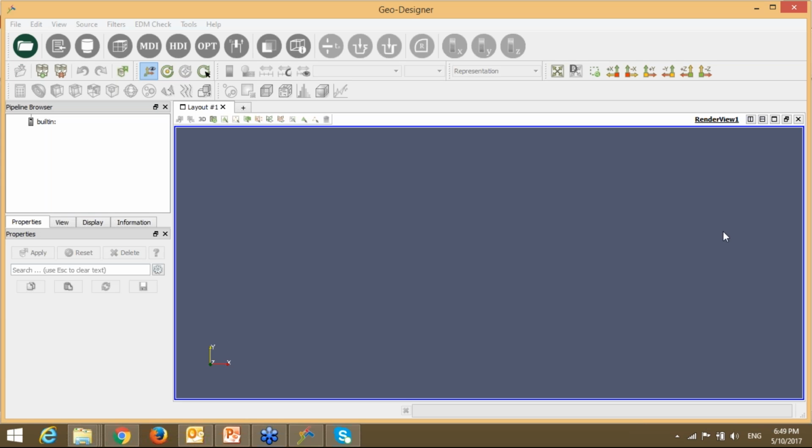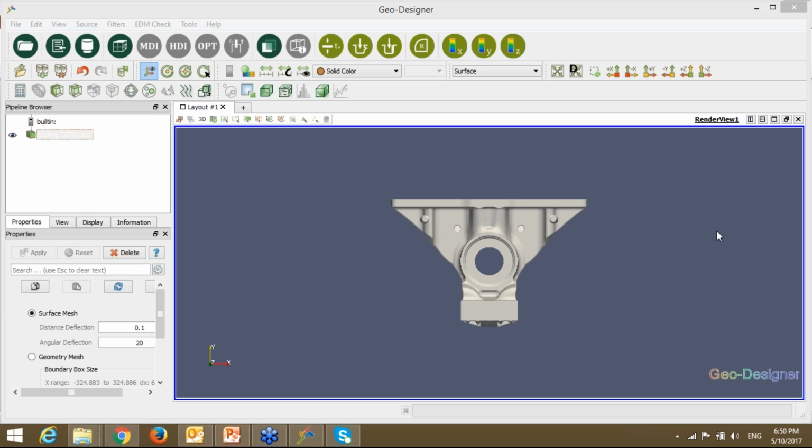Okay, one more question. Is there any effect of the core part in the actual hotspot section? No. Basically, the core is in connection with the casting part, or even the sand mold is in connection with the casting part. But what we are analyzing here is the pattern of solidification. That pattern of solidification will solidify irrespective of the core location or irrespective of the sand which is in connection with the casting part.